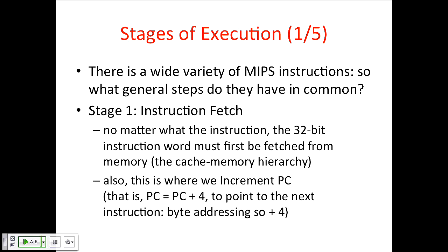Also at the same point in time, we'll actually increment the program counter and add 4 to it in MIPS to move on to the next address to get ready for the next instruction fetch. Question?